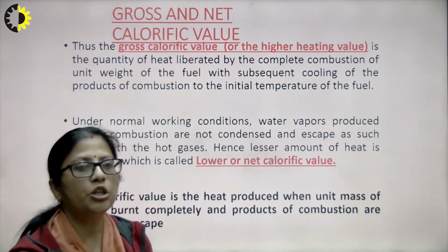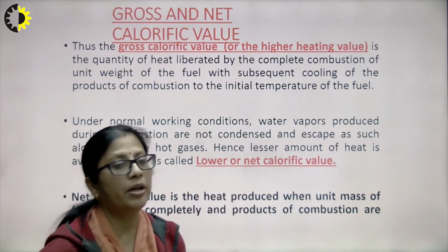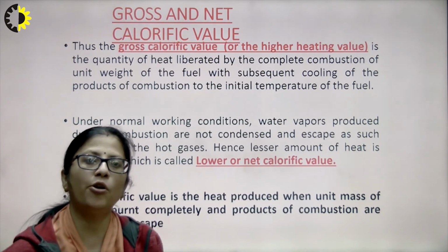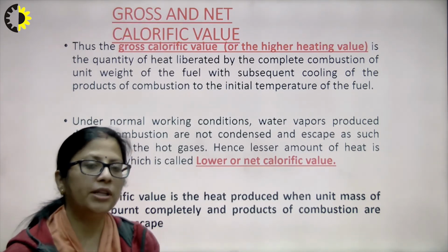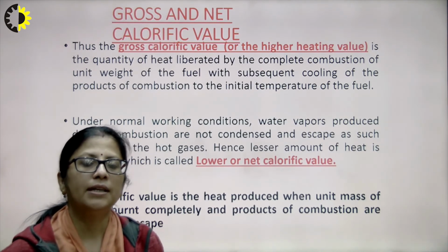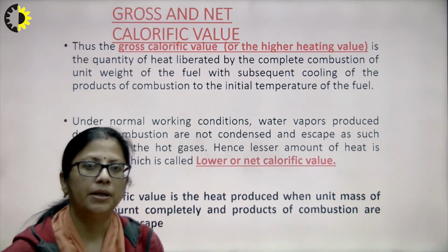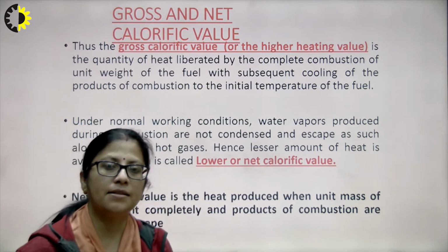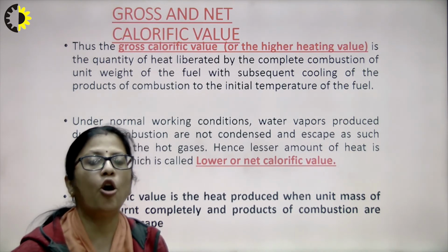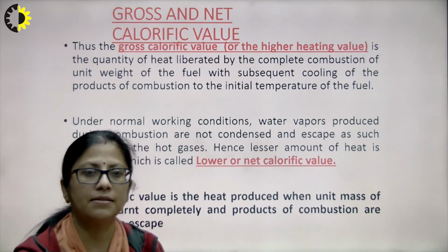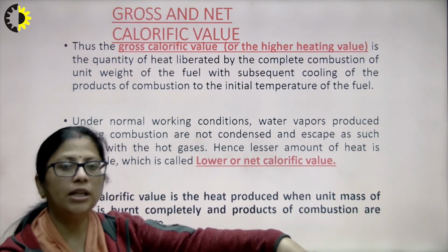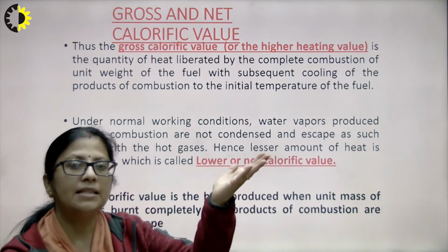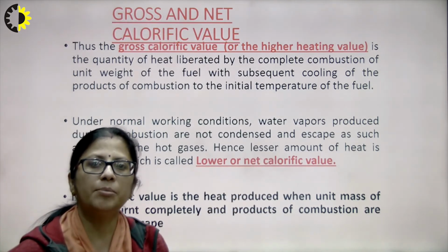But in normal conditions, water vapor is produced during combustion. Since hydrogen is present in all the fuels, during the combustion process this hydrogen gets converted into water vapor, and this water vapor is not condensed, and it escapes along with the hot combustible gases. If I burn wood in the open, I am not condensing any water vapor. This water vapor escapes along with the hot combustible gases.